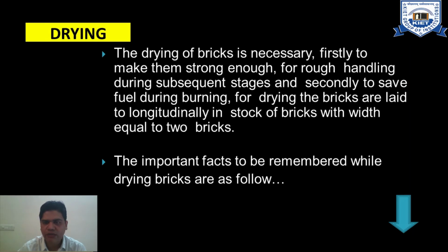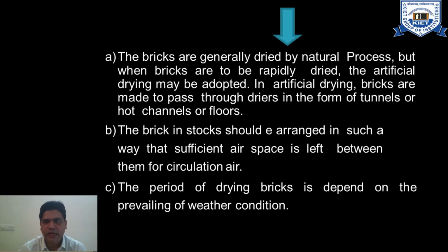The important facts to be remembered while drying bricks are as follows. The bricks are generally dried by natural process, but when bricks are to be rapidly dried, artificial drying may be adopted. In artificial drying, the bricks are made to pass through dryers in the form of tunnels or hot channels or floors. The bricks in stacks should be arranged in such a way that sufficient air space is left between them for circulation of air. The period of drying bricks depends on the prevailing weather conditions.